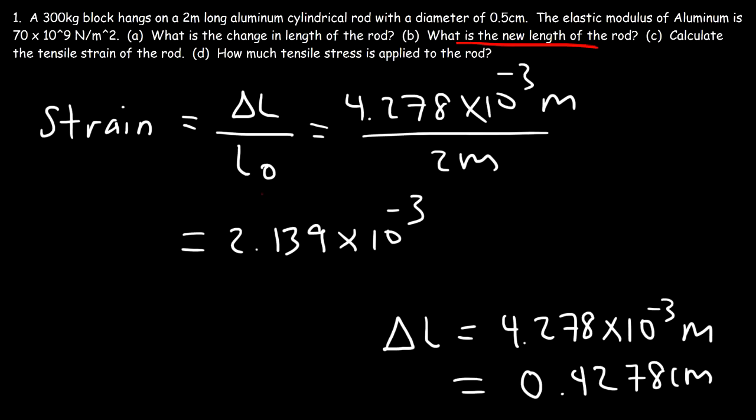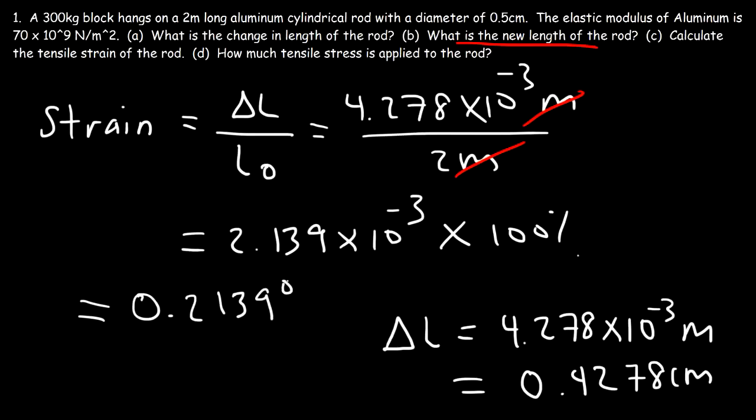Notice that the tensile strain is unitless. So if you want to turn this into a percentage, multiply by 100%. So that's 0.002139 times 100. And so the length really changed by maybe about 0.21%. So it didn't change much.